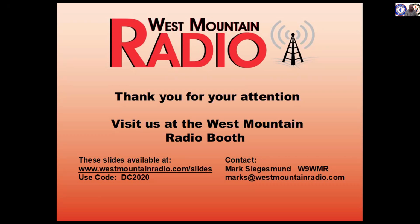Very good. Thank you. With regard to solar, are you doing anything with inverters in addition to the chargers that you have? We have not. We have people that periodically ask us about that because they've got AC needs as well. We've been afraid of inverters because of the RF noise. Yes. And doing one that's going to be suitable for amateur radio use is going to be a tough deal. We went through that when we came out with the Epic, because it's got that MPPT controller in it, which has got the same problem. And we went through a lot of work to make that noise-free RF-wise. But a regular inverter, that's going to be a tough sell.